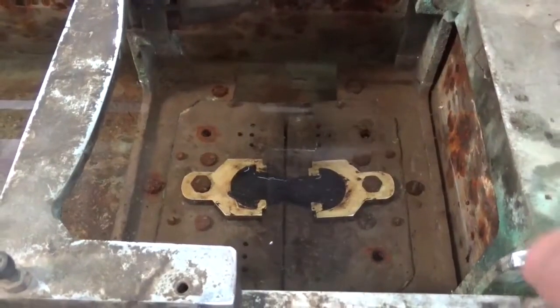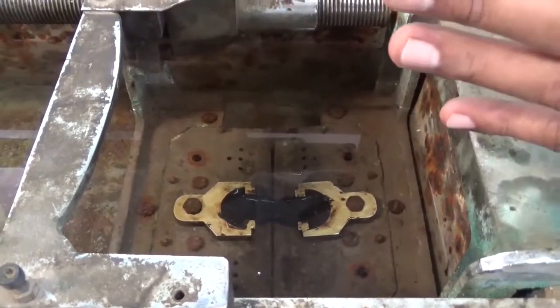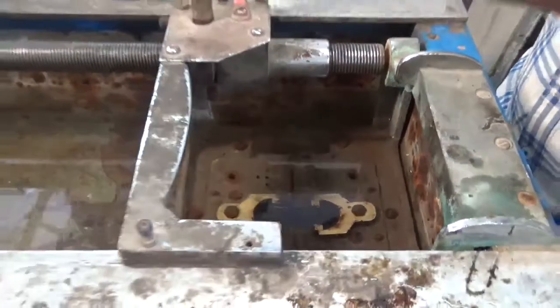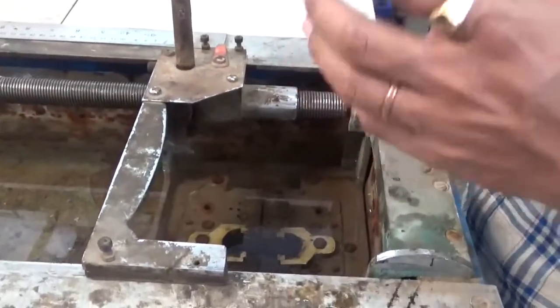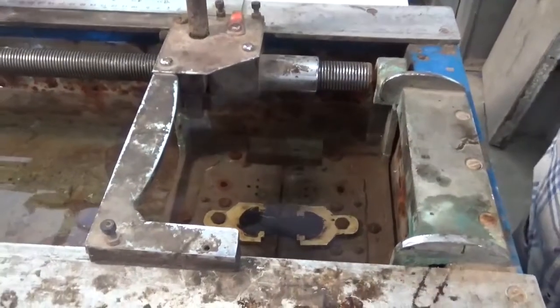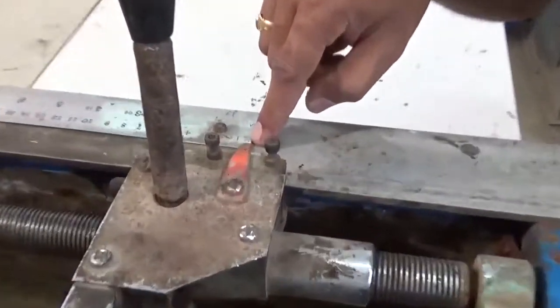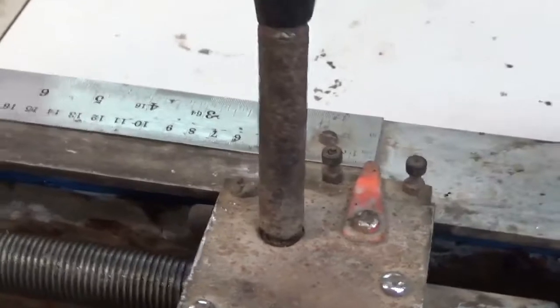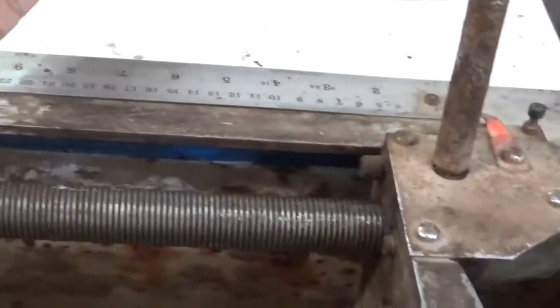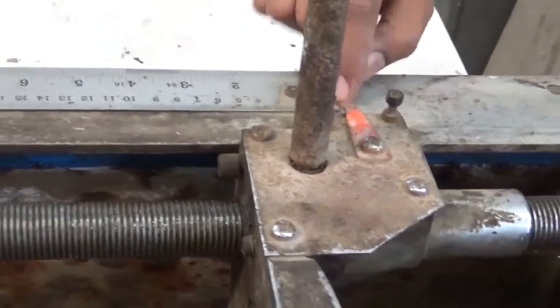The hour has already passed. Now we are going to pull this sample at the standard mentioned pull, that is 50 mm per minute. The temperature of the water bath, as I mentioned, the test should be done at 25 degrees centigrade. So the temperature is around 25 degrees centigrade. My marker is at 0. This is my scale, and with the help of the scale I can measure the ductility. Right now my marker is at 0, and I am going to start the machine, and we will see how this